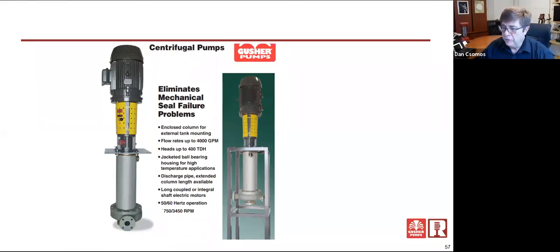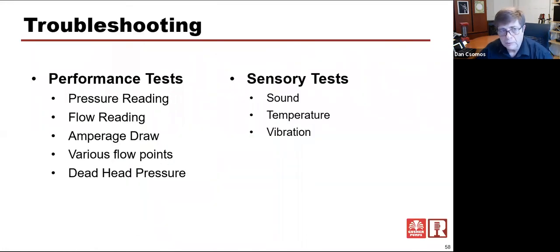Okay, so I turned my video back on because I'm going to show you a couple things as we go forward. We're actually going to get into some troubleshooting of these pumps and systems. And in performance tests, as tools to you, what do you have? You have pressure reading off a pressure gauge. That's the most common thing that you're going to be able to look at to determine where a pump's running at, what condition it's running at.